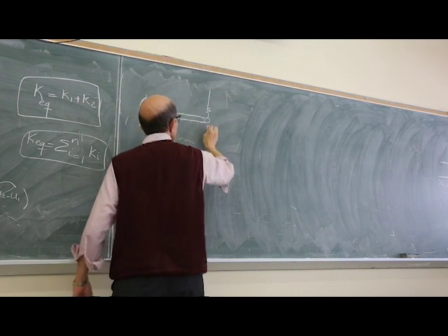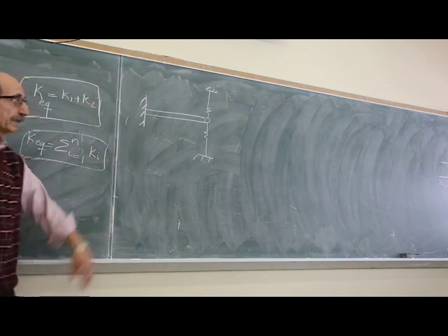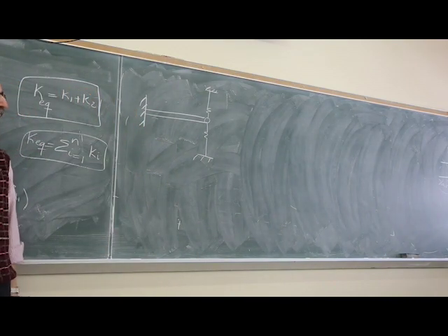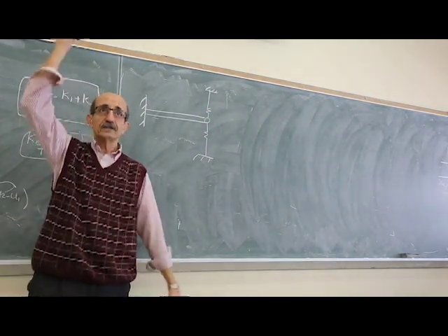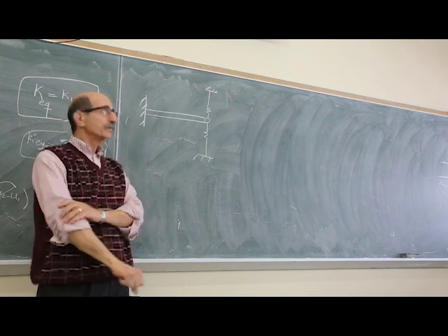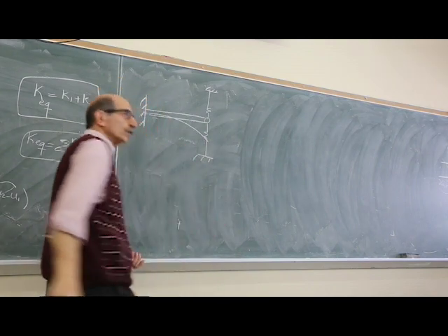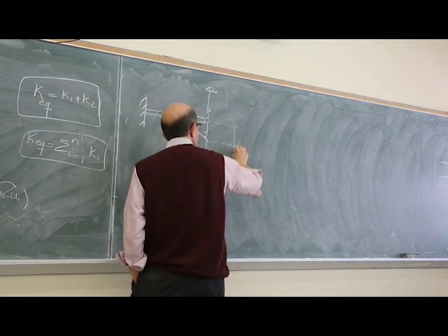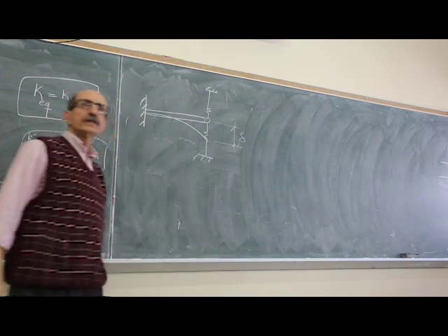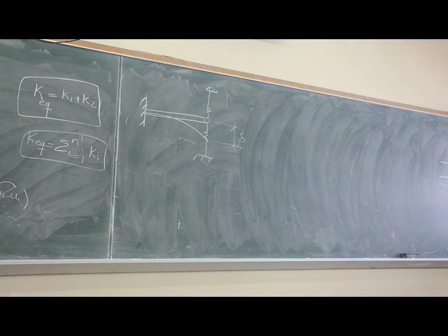And two springs like this are connected to the tip, and this is oscillating, right? You would say these two are in series, right? Because they're connected in series. But that's not true. Look at the whole system. If the system is going through some deformation, this beam would go through this deformation, delta, that those springs also experience. So all these three pieces are actually in parallel.